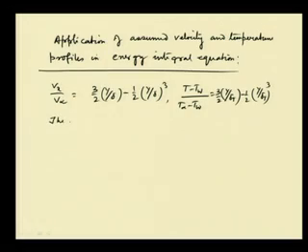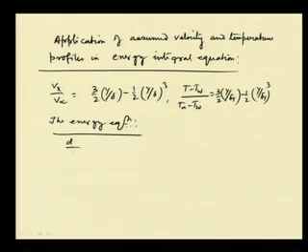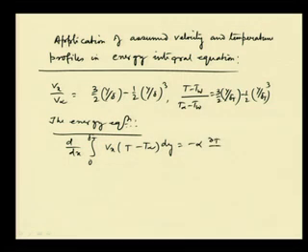Now, the energy equation that we have developed is d dx of the integral from 0 to delta T, where we have also said that the limit is from 0 to delta T, delta T being the thermal boundary layer thickness, of Vx into T minus T infinity into dy, and that is equal to minus alpha into del T by del y at y equals 0.